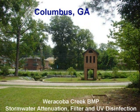At each plant, one of them also responds to a wet weather event. They're called on their cell phones and told, hey, we have a probable event. They go down to the facility just to monitor and make sure everything's working. It runs by itself, but they still do the logging of how the equipment is running. Sometimes they have to implement the upstream and downstream sampling. Then the samples are picked up by the laboratory to do the performance analysis and the reporting. In terms of O&M costs, on a present worth basis, it's about 6% of the capital cost, which is a very low figure.